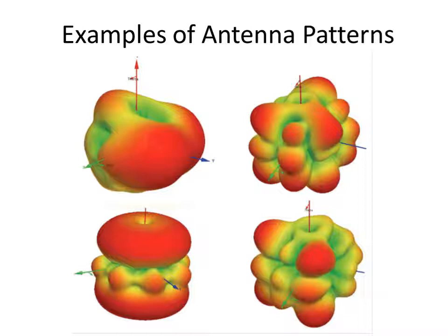Please also note that here antenna patterns are not used in the conventional sense of RF engineering to steer the beam and focus the energy. These are just essentially to create randomness, and it doesn't matter the shape of the pattern. All that we want is that the patterns differ from each other such that each pattern will correspond to a new random phase.